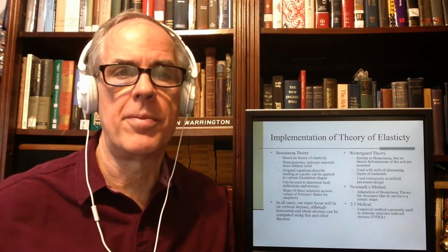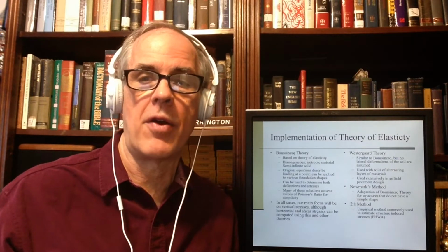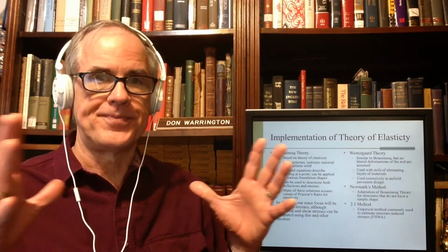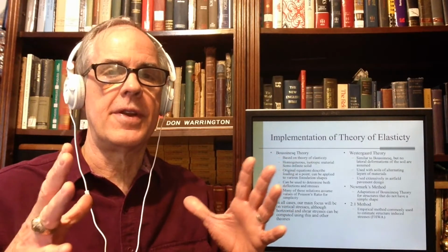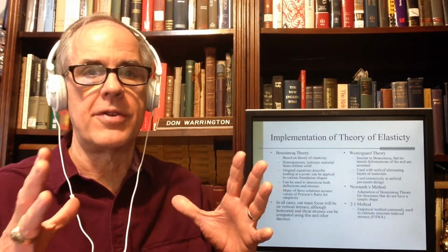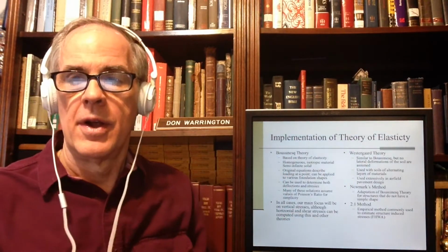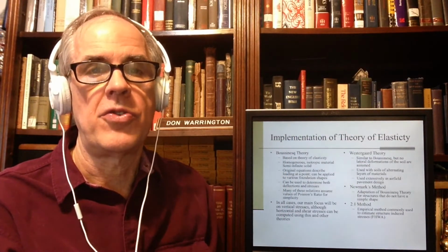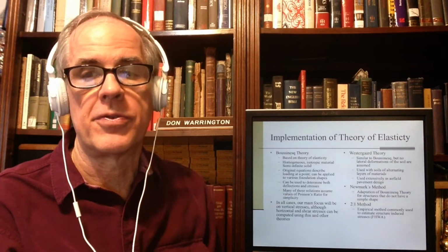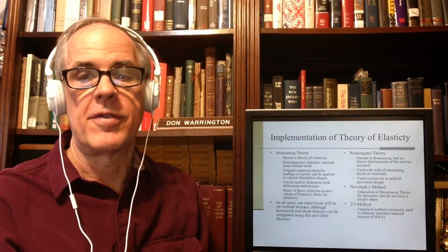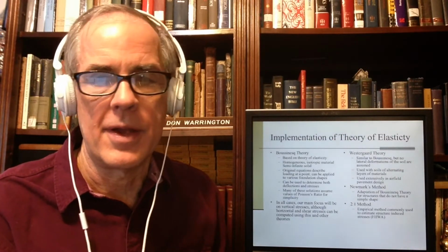Westergaard theory is similar to Boussinesq, except that there are no lateral deformations of the soil. In other words, it assumes the soil is semi-infinite, so that because the soil way out here doesn't move, it confines the soil in here. It is used in soils of alternating layers of materials, which Boussinesq doesn't handle, and it is used extensively in airfield pavements. I'm not going to talk about that.